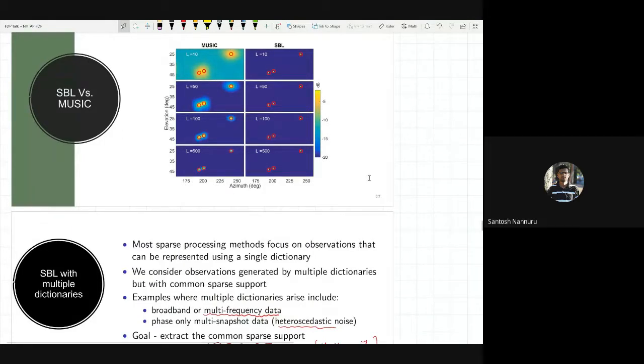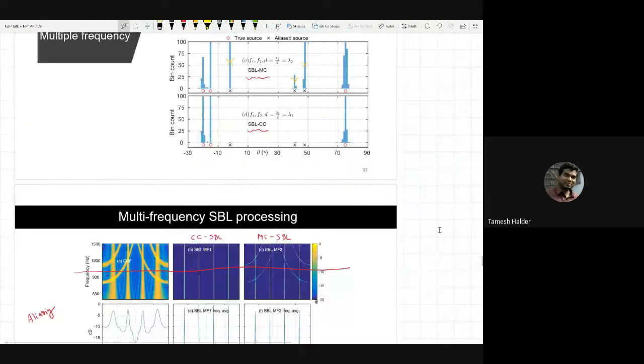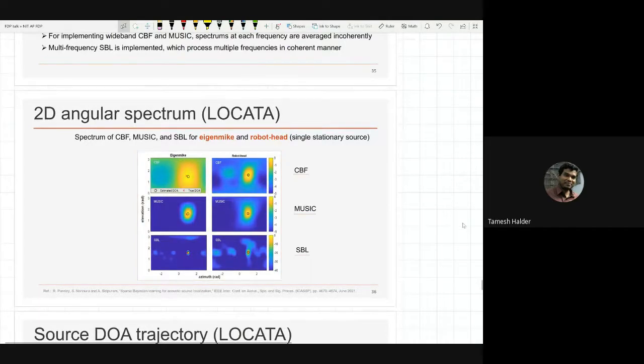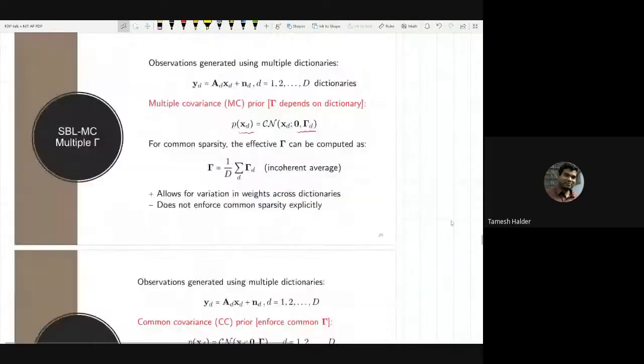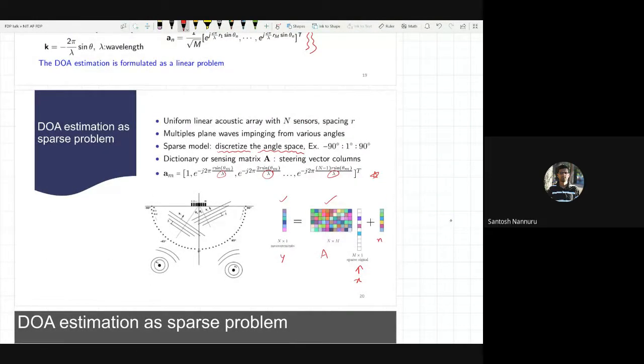Azimuth and elevation are conventions which are used, but they could be any two angles. I am asking how they are jointly estimated, because the sine theta is either for elevation or for azimuth. So, sir, how can this plot be achieved by jointly localizing both of them? When there are two angles to find, this is not the formula. This formula only works when you're finding one angle. If you have two angles, the formula changes, and you will have two angles explicitly in the formula itself, for example sine theta cos phi, with two terms. I understood, but maybe the formula is in the Cartesian domain, or maybe in the spherical domain, right, sir?